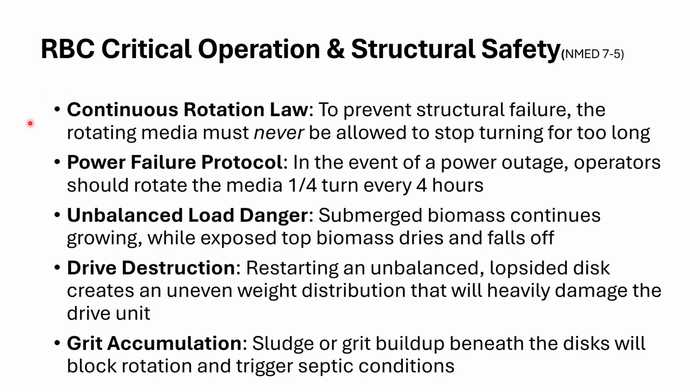So here's the thing, a couple of very important points when we operate these. There's this thing called the continuous rotation law for an RBC. We've got these drums or barrels suspended with a center shaft and some bearings. We don't want those things standing still too long. If we do that, those bearings are going to fail. We're going to create a problem for ourselves. So we don't want to leave these stationary for too long.